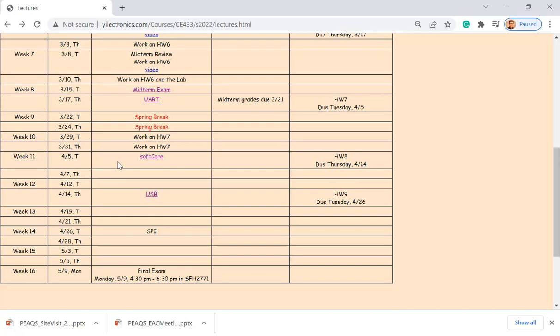Not every company is making ASICs, which is doing the layouts and fabricating chips, which cost a lot of money for the company to prototype one IC design, usually millions of dollars for the 20 nanometer technology. So it's a lot of money. And if they have a bug on the chip, probably $2 million is gone. That's the reality. So usually they prototype SoCs on FPGAs first before they send it out for fabrication. So that's why FPGA is getting so popular.